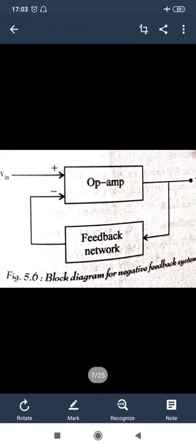So we use the concept of feedback, where we take some fraction of the output and give it to the input through some linear element or directly coupled. We give the output to the input in two ways: negative feedback and positive feedback. In negative feedback, we feed a fraction of the output to the input via a feedback network, and the op-amp is our active device.